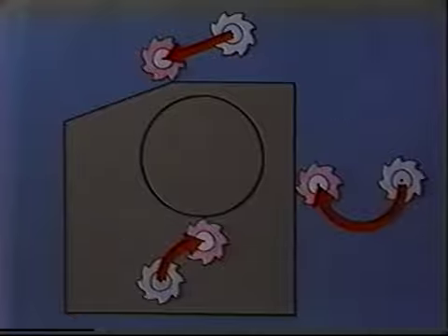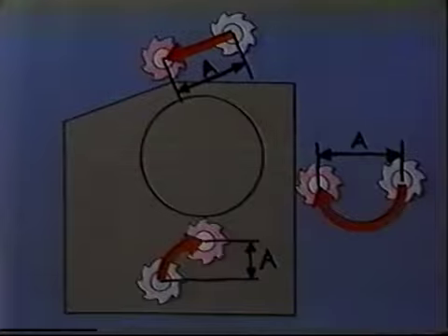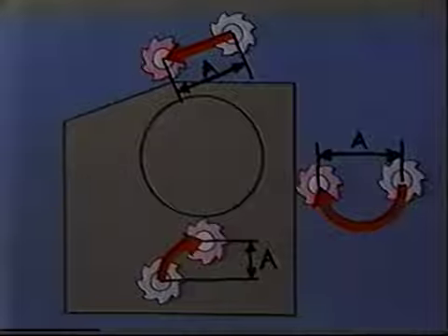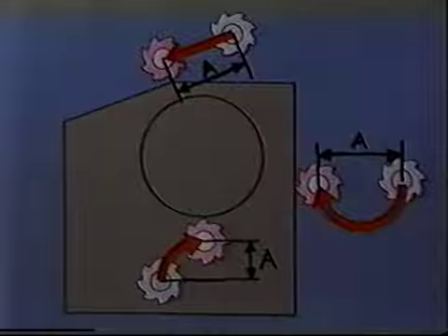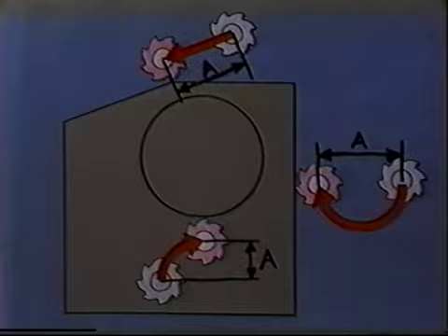Why don't I try putting in a 5 for G45? Now I got an A. What's that? A simply stands for programming the spacing between the down feed point and the first contour point. In other words, if the user inputs this spacing to the control system, the system automatically calculates the required down feed point and then leads the tool along the desired path, approaching the contour tangentially. Now I'll give it 10 millimeters.